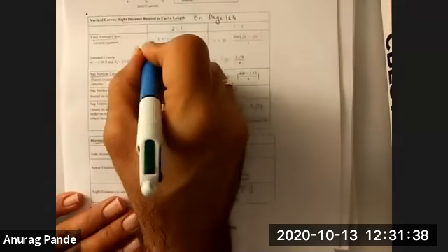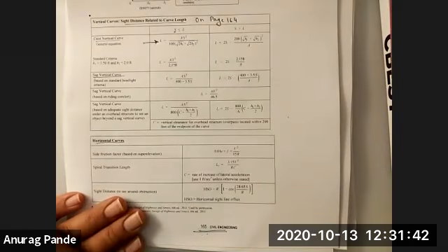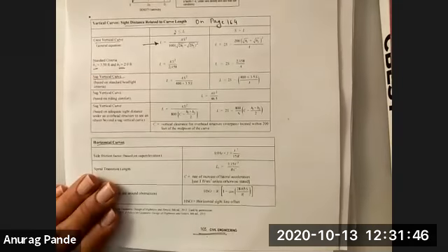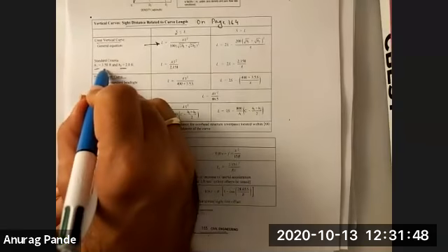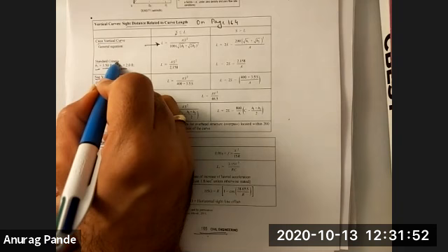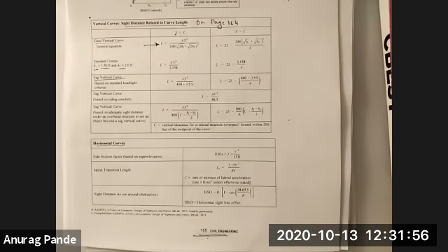And remember, this is the generic formula. But if they don't give you some values like H1 and H2, which I'm going to define in a second, you can use the standard criteria values that are defined in the AASHTO Green Book. I know Caltrans sometimes uses different values, but in the FE exam that is not relevant right now. We'll just go by the AASHTO Green Book, which is the national design guideline on streets.